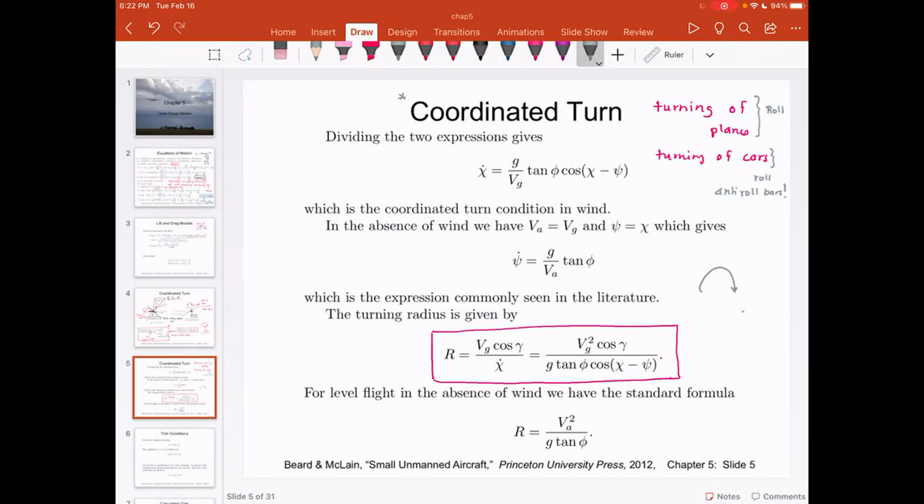When you have a ground vehicle, you will notice that this roll motion is compensated or not desired, and you have anti-roll bars that would prevent the car from rolling over. That's why when you are driving an SUV, you will see the sticker on the back of the windshield or visor. It says high rollover risk. So be careful while turning. That is the reason why, when we look at the turning or yawing of aircraft, we look at the coordinated turn.